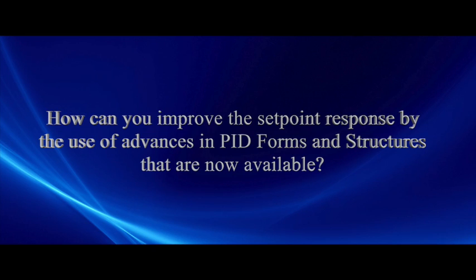With the older versions, you didn't have all the options of set point weight, gammas, and beta factors. So you really didn't have an opportunity to tune for a load response and then optimize the set point response. You didn't have that option.